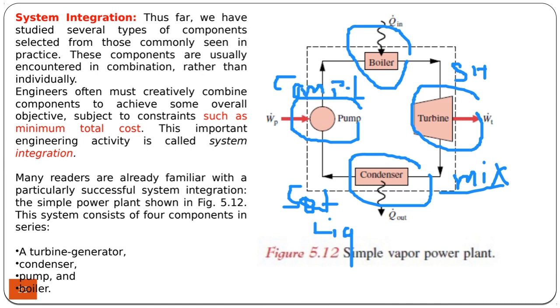And this compressed liquid leaves the boiler as superheated vapor, and it becomes a complete cycle. So the purpose of the cycle is to deliver work, and this work can drive a generator or a shaft of a ship propeller, for instance.